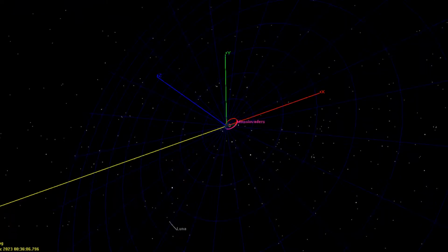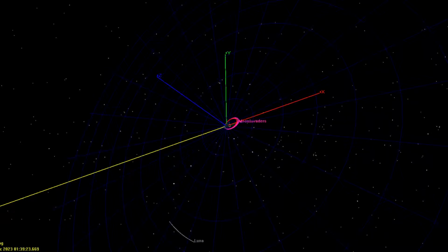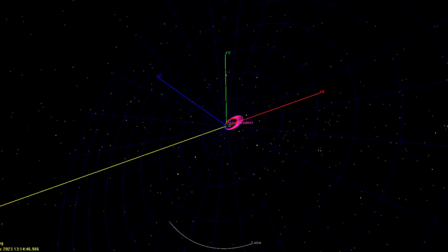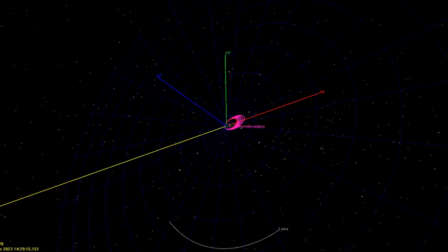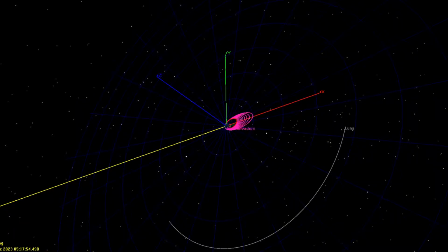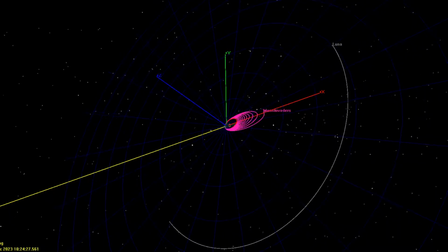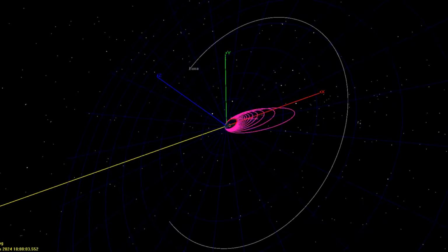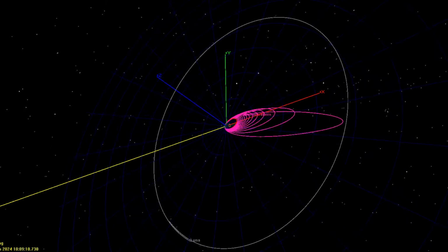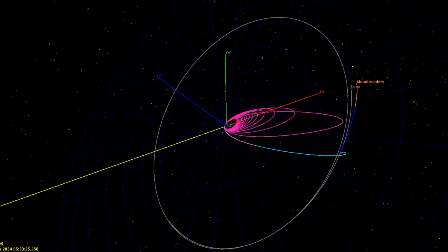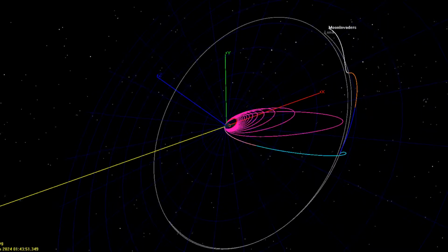At the beginning of the fourth mission phase, the satellite is at the point with true anomaly of 160 degrees. From this point, we create a target maneuver which will allow the CubeSat to perform a polar flyby in the Moon. Using the GMAT software, we can define the burn time and the velocity values for the 3 directions as variables. In order to make the satellite do a polar flyby, we need to constrain the maneuver with the objective of performing a hyperbolic orbit around the Moon.